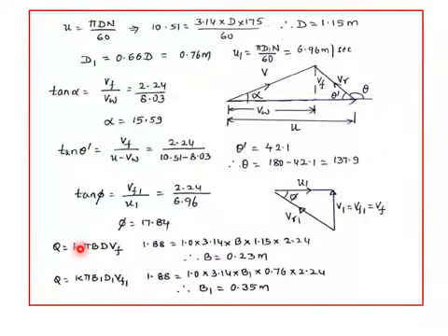If 10% of the area is blocked, then we write it as 0.9. Here nothing is mentioned about that, so therefore we can take K is equal to 1. B is the width of the wheel or the runner, and D is the diameter, so with the velocity of flow, the B can be calculated. Similarly, the same discharge has to pass even at the outlet. So here the corresponding width, corresponding diameter and corresponding velocity of flow are taken, so you can calculate B1.